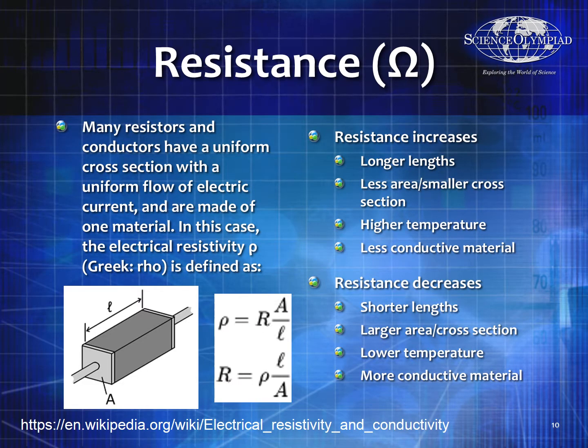Now, when you look at a resistor, it's a little bit like the capacitance problems. Resistance is usually defined by the material, the surface area, and the length of the material. So R is equal to rho times L divided by A, where rho is the resistivity of the medium. You'll have very low resistance for conductors like copper, very high resistance for insulators. And then they'll often use semiconductors, which have medium resistance, for actually making resistors. L is the length and A is the area.